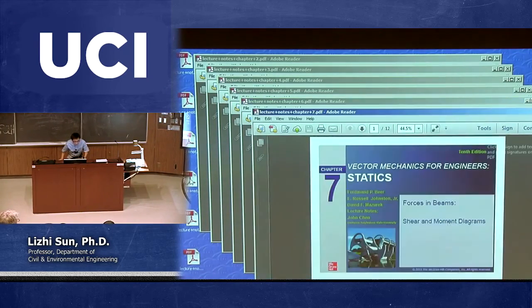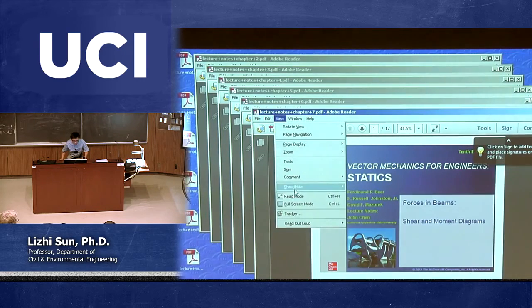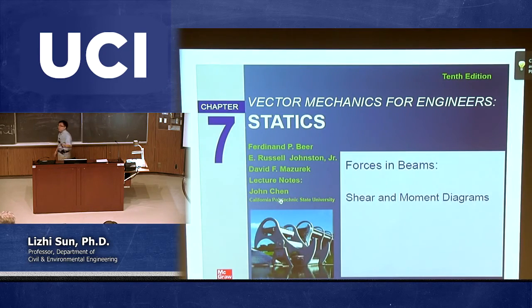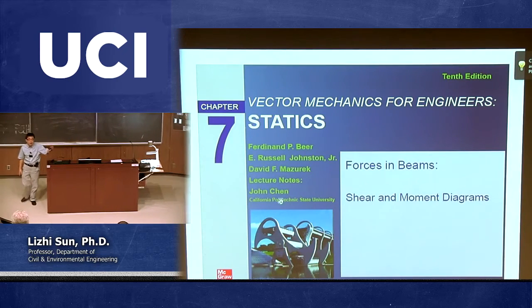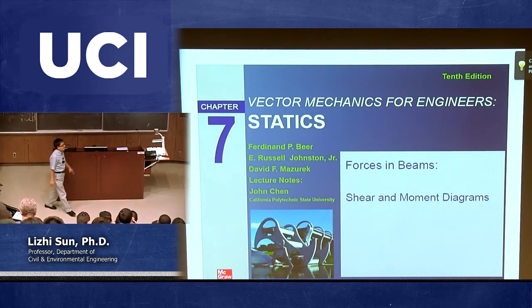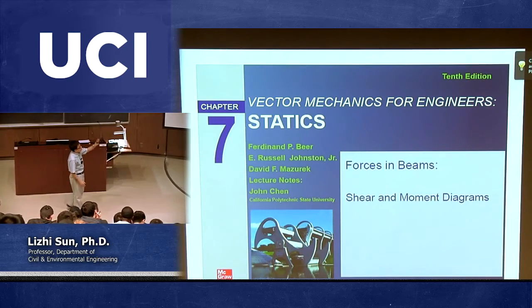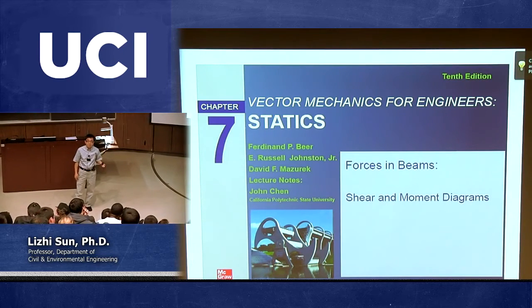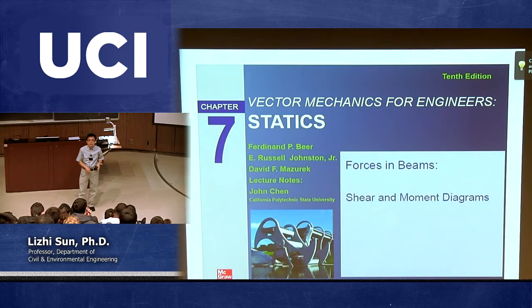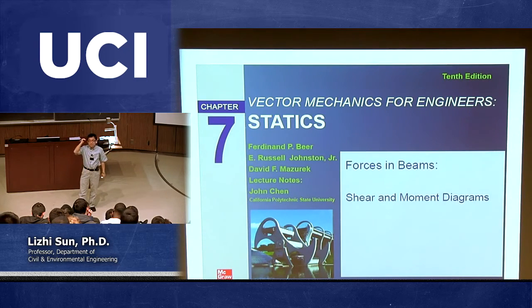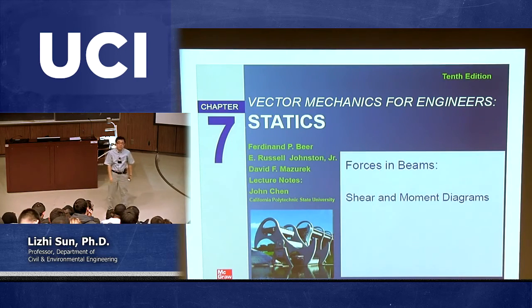That's, I believe, the most important part, which is to plot the shear and the moment diagram. So I guarantee you're going to have one complete question asking you to plot shear and the moment diagram in the final exam. It's going to be a complete question. Okay, I give you 2 pages basically, to solve such a problem. So that's why you should not only plot. You should give me the procedures. Okay, step 1, to calculate the reactions most likely, right? And then you're going to decide how many segments you need to cut. Okay, for each segment, write down those equations.